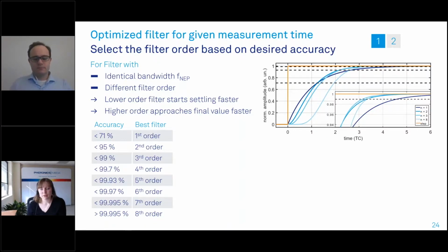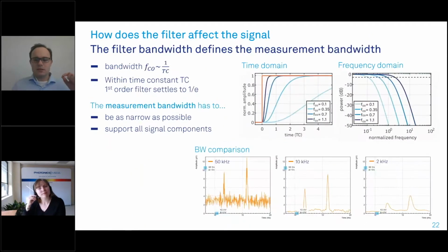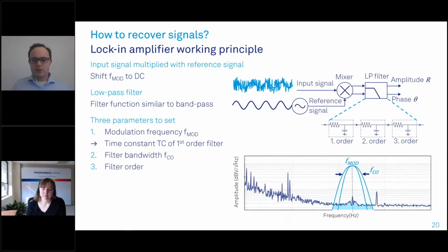How do you determine the frequency and the amplitudes of the reference signal in lock-in amplifiers? This is a really great question. I would like to go back to the slide. What is of course of high relevance is at which frequency we want to detect, and this is only relevant if the lock-in itself does not provide the reference signal.